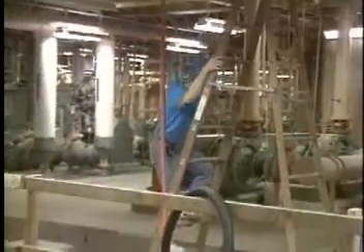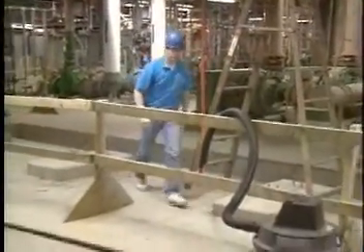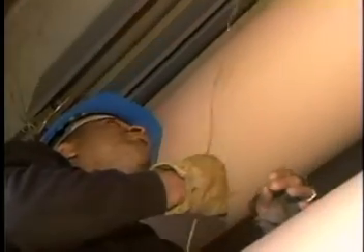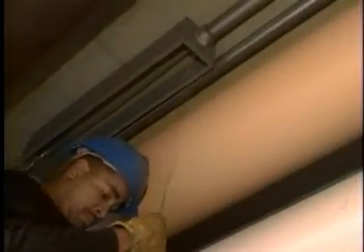A lightweight nylon cord is attached to a piston or mouse and is fed into one end of the duct. At the other end, a large shop-style vacuum cleaner is attached, which draws the piston and pulling line through the duct. This process works with empty ducts or with ducts containing existing cables. It can place several hundred feet of pulling line in a few minutes.